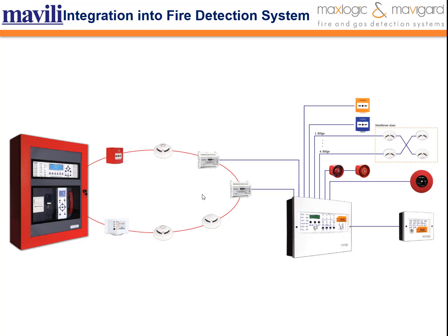So, if you use both detection and extinguishing systems in your projects, our solution is connecting both systems via our input modules. So, for one extinguishing system, you need to use 3 input modules. It allows you to monitor your extinguishing system in addressable panels.